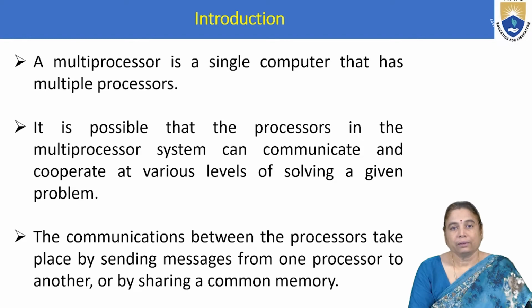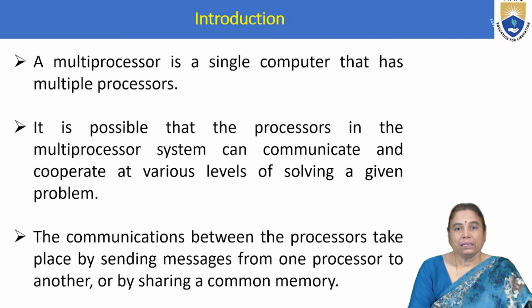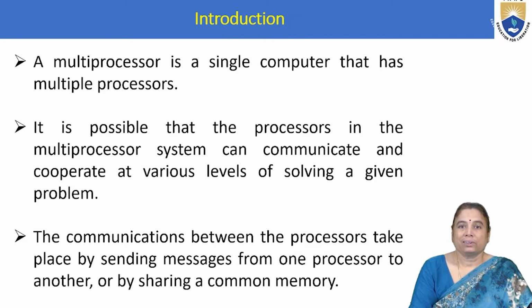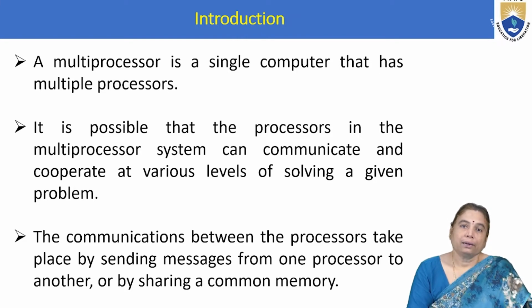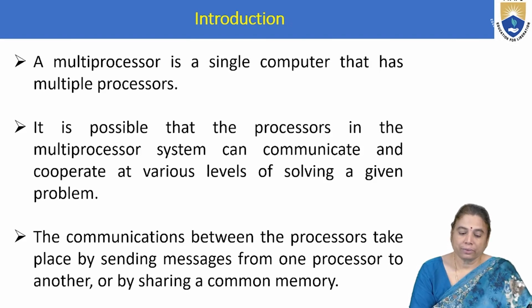At the third clock signal, the first instruction can move to the calculation of the effective address and fetching the operands, the second instruction can move to the decode step of the instruction cycle, and the third instruction initiates the fetching of the instruction. In this way, multiple instructions can be concurrently executed.